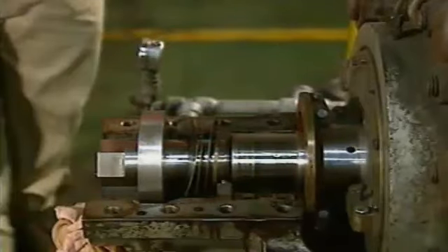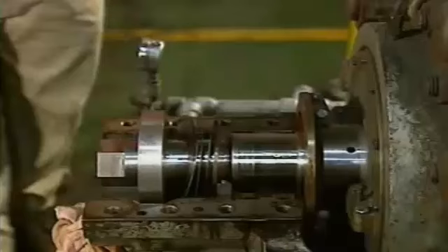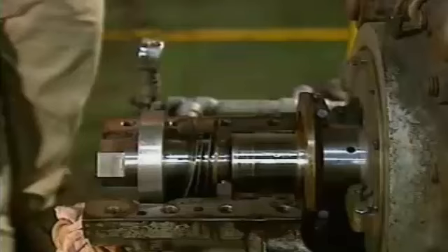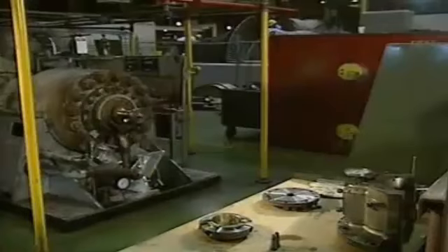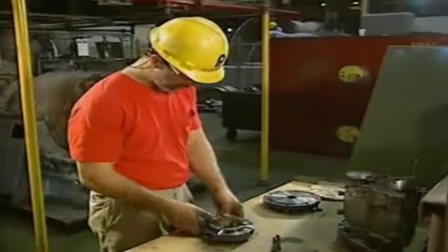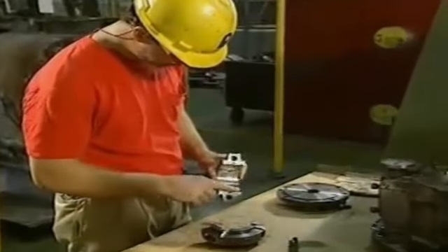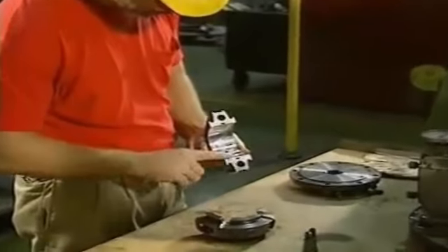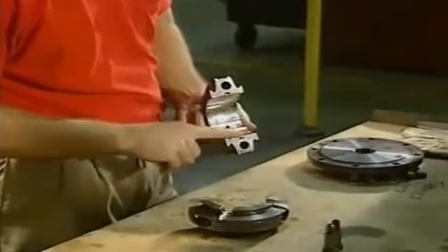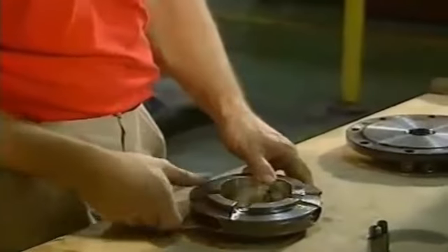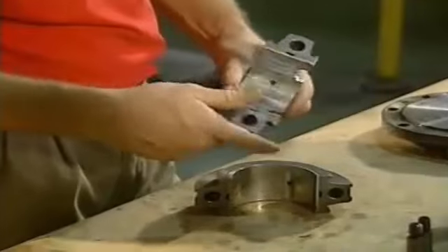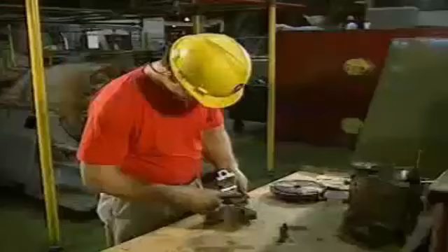After the bearing has been removed, the shaft is inspected for high spots, scoring, or discoloration. If there is deep scoring, the shaft should be remachined or replaced. After the mechanic inspects the shaft, he inspects the bearing inserts. He pays particular attention to the lower insert because it typically bears more load. He checks the inserts for scoring, high spots, wiping, or discoloration.